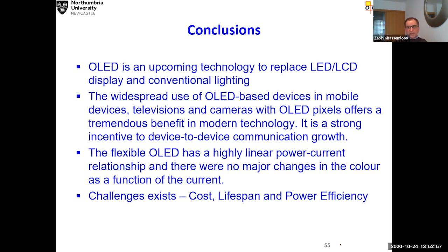At the moment, compared to standard inorganic devices, they are still high cost. But manufacturers are, of course, working on it all the time, and it's possible that in the next few years they'll be at the same price as the standard LED. So do show an interest, get some of these, take them to the lab and do basic experiments with them. Don't push for the high data rate. Try to send things at a few kilobits or even megabits per second, get the concept down, and see, using that low bandwidth, how much information you can pump into it, to go to around 200 megahertz if you can.